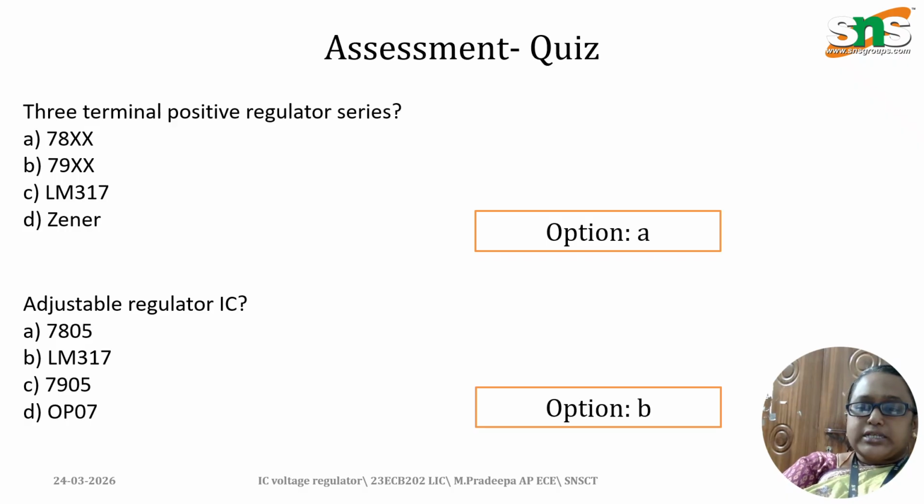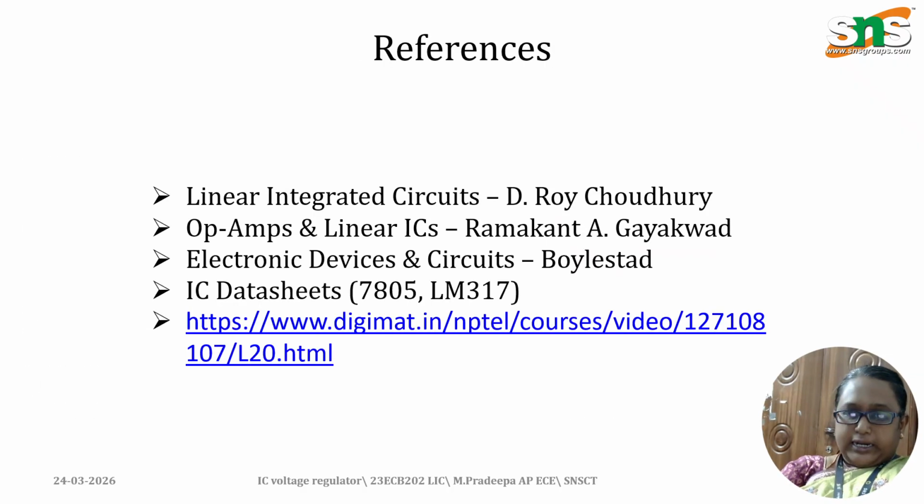Previously people might use the Zener diode for voltage regulation, whereas PN junction diodes are highly used for rectification, AC to DC, whereas Zener diodes are highly used for voltage regulation to give a constant voltage supply and also to maintain proper load variations in real-time application working, and in order to avoid short circuits, we will be using proper IC voltage regulators.